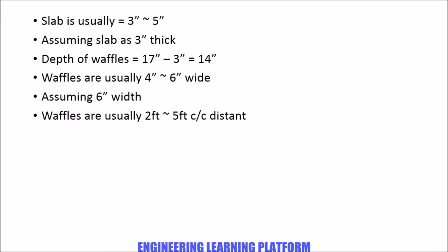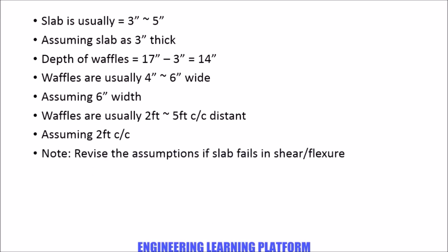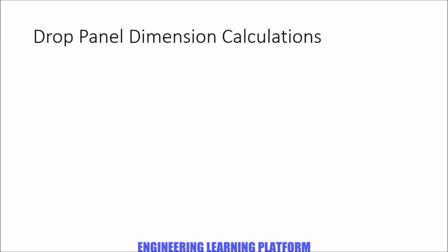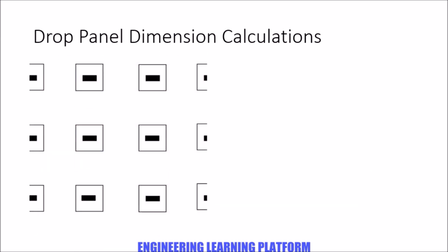So assuming the width of the waffles as 6 inch, the waffle's center to center spacing is 2 feet. We may revise the assumptions if the slab fails in shear and flexure, which we will check for in the later part of the video.